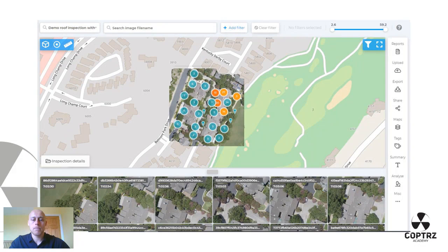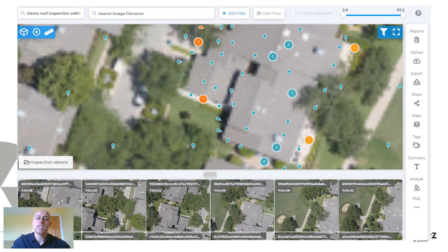And what that gives you is you can almost tell that there's been a flight path around there, and it will input the actual photos from Google Maps, or if you are using Pix4D, you can import them onto the software. So it'll give you an overview of the building that you are doing. And then if you click on one of the single points, you can see the direction of all the photos that were taken. And you can see that in the middle.